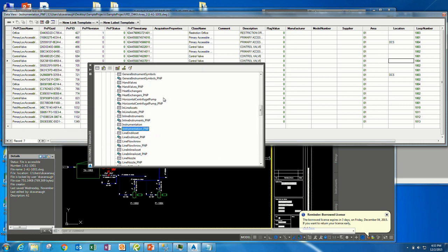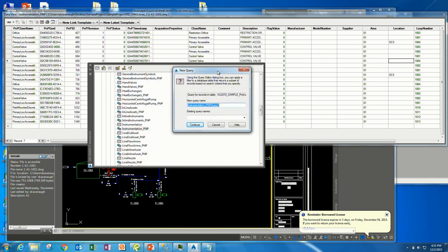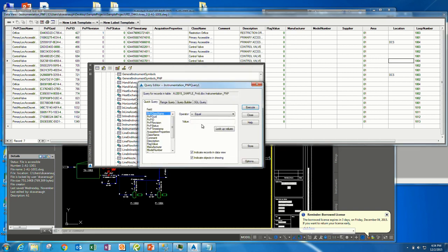So now that we have that link into our database, we can then start playing with things. You can run a query, and queries are nice because they're repeatable. You can create a search query: tell me how many flow meters do I have in my project, how many valves do I have in my project, and you can save those, and it's repeatable with the data manager. If you want a specific format, you've got to go in, create a new template, do this, that, or the other, hop into project manager. I find it unnecessary. So here's my new query.